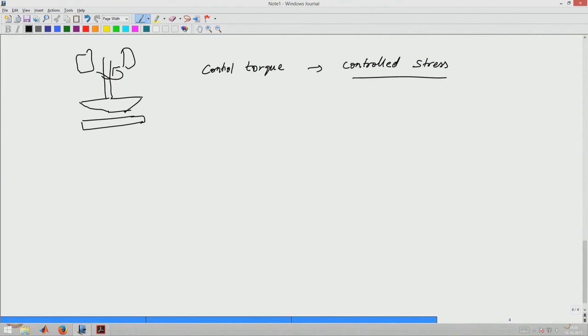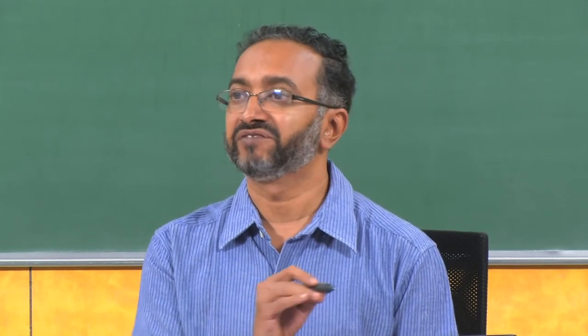So, the manipulation of friction in the case of rheometers is very crucial, because a lot of the torque otherwise will go in overcoming friction, and more importantly this torque may depend on the rotation rate, right. So, therefore, there will be many uncertainties associated with managing friction in such rotating geometries.